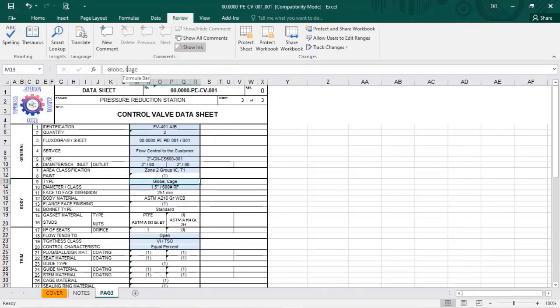During your practice, you can change the valve type and see if the software responds to you with a valve suitable for the process conditions. And in this case, we have a 2 inches control valve with 200 pounds class. Another interesting information that you should know is how fluid goes through the valve. In this case, it goes from bottom to the up, and because of that, the flow tends to open the valve instead of closing the valve.